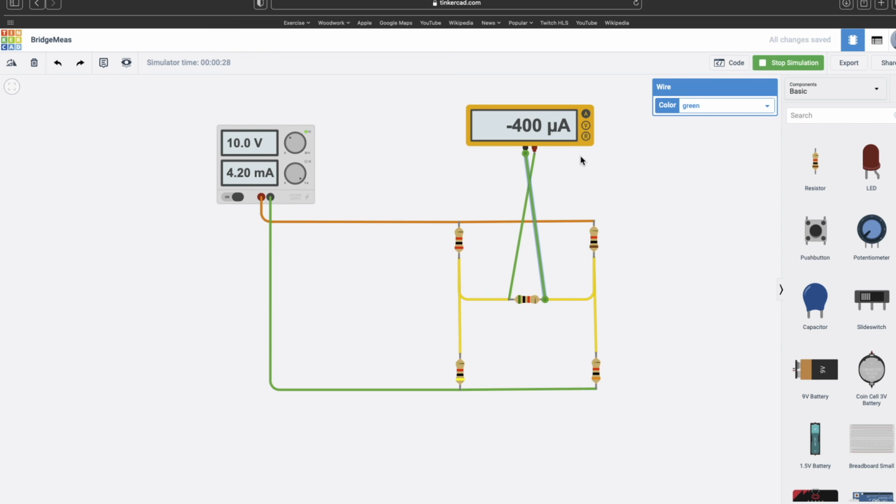It can, in fact, in real circuits, you can end up, because you get larger currents, if you put it across the supply here, we could, in fact, damage the ammeter totally. So it's something that you should not do, is put ammeters in just in parallel. Remember that to put an ammeter in, you need to break the circuit first. You don't put it in just with 2 wires across things once the circuit's built.